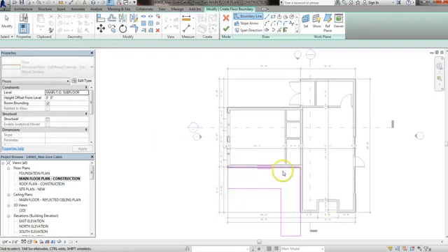And the thing about this is that it's going to be 3 inches down from the main top of plate. That's kind of a standard. Some people actually do, it depends on what the code is and where you're from. Sometimes it's 1 1/4 inch. Sometimes it's just 1. We just normally do 3 inches down from your door.